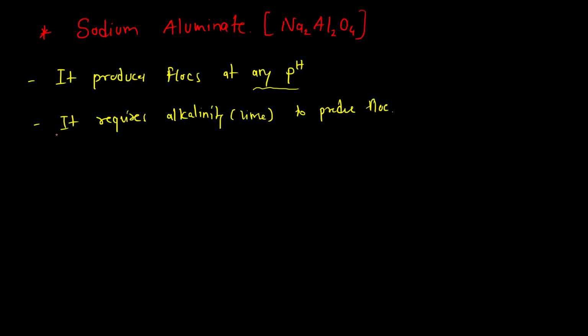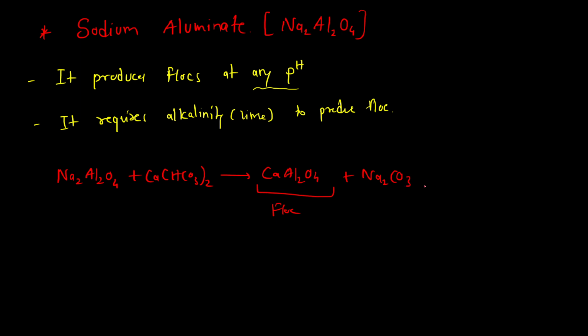Now the equation for this is Na2Al2O4 plus calcium bicarbonate, which gives CaAl2O4, which is the floc, plus Na2CO3 plus CO2 plus H2O.